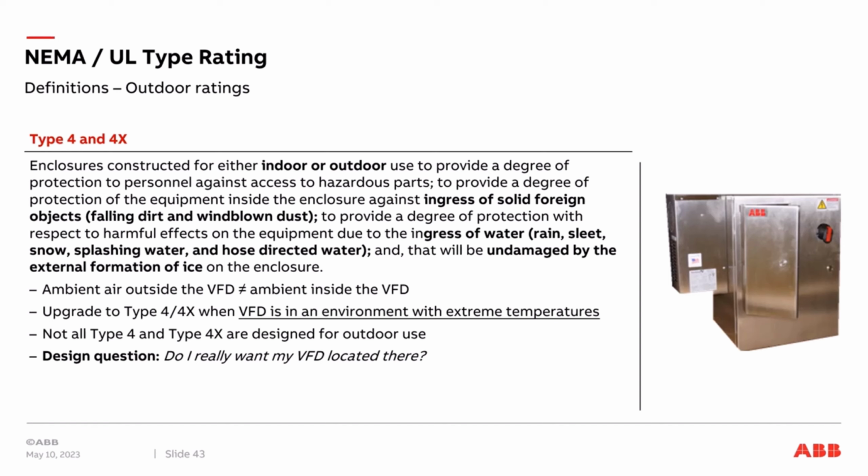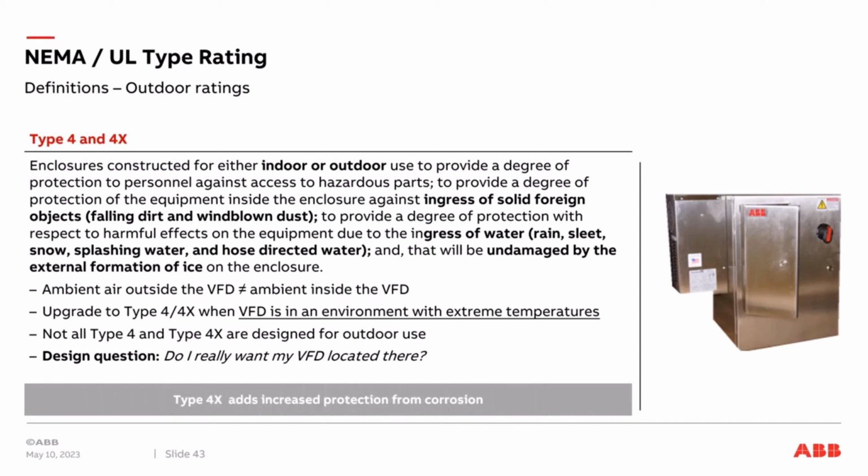It depends if they're designed for sun loading. The real question you have to ask yourself is, do you want to put the VFD where the location requires a 4 or 4X enclosure? Now, when we go from a 4 to 4X, we add increased protection from corrosion.